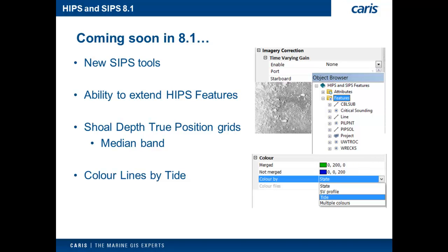For processing, we borrowed some technology from the multi-beam side of things. So all of the side scan processes now take advantage of multi-threaded processing, which actually made it fast enough to do it on the fly inside the side scan editor or waterfall display. Previously, you'd run a slant range correction and then you'd wait, and then you'd run a beam pattern correction and wait. Now you simply check or uncheck a box and you see the results right away without waiting for those processes to complete.